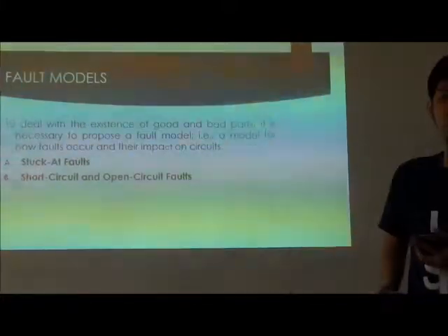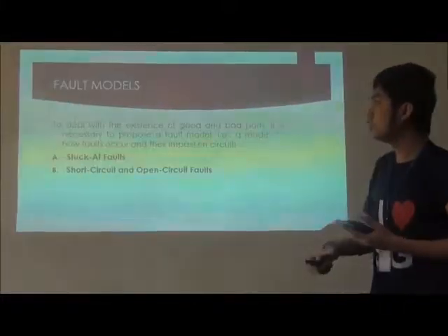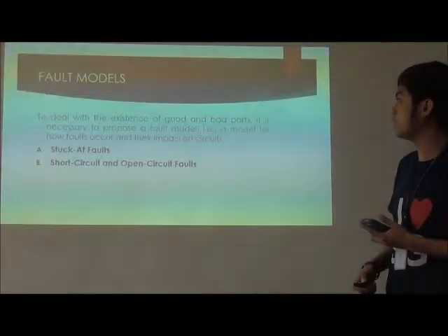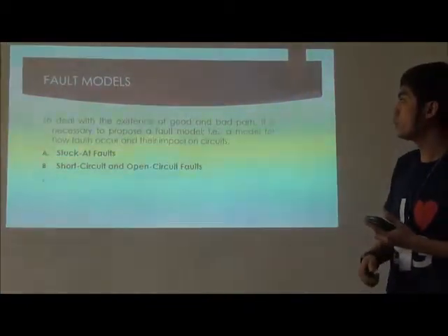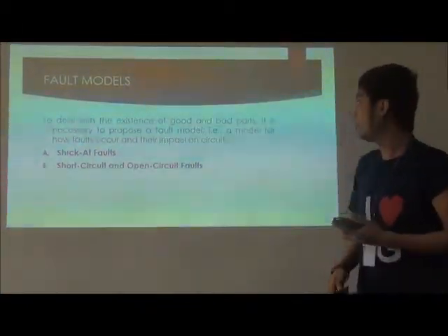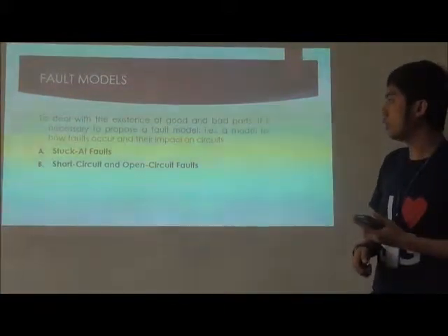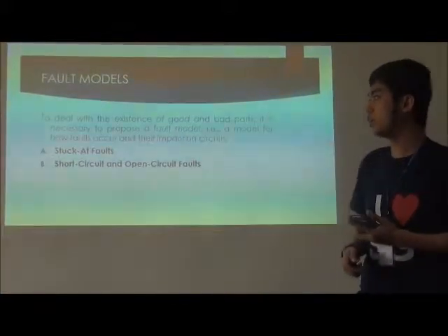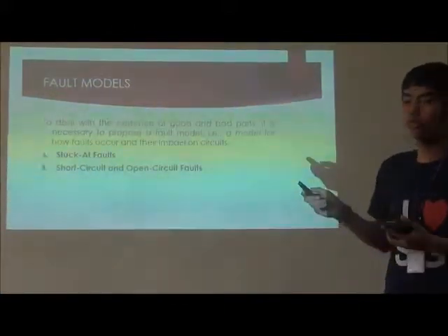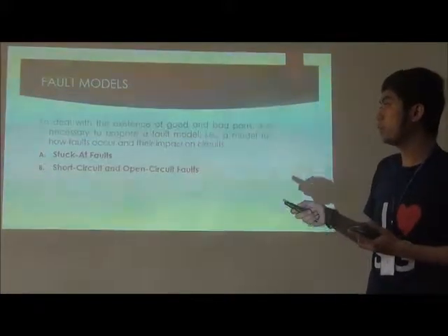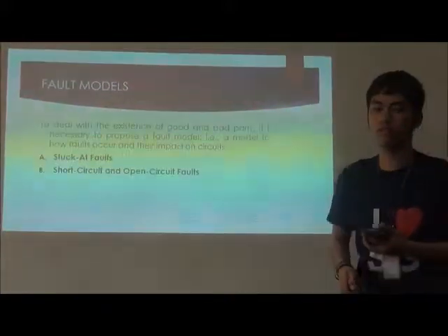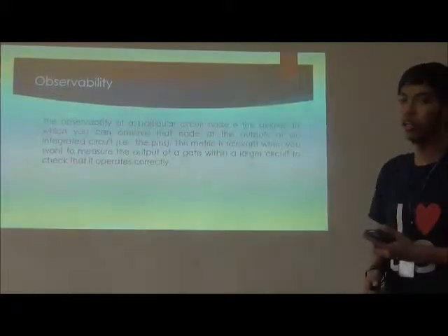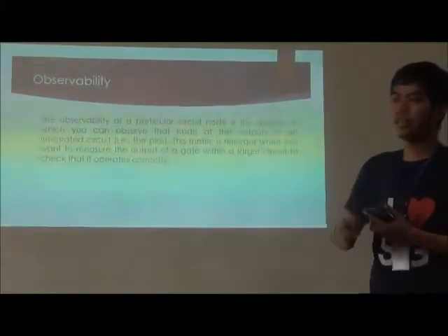So, fault models. To deal with the existence of good and bad parts, it is necessary to propose a fault model, for example, a model for how faults occur and impact circuits. So we have stuck-at faults, short circuit and open circuit faults. These are the factors to be considered.